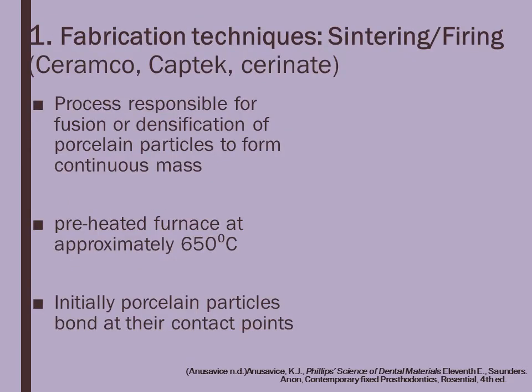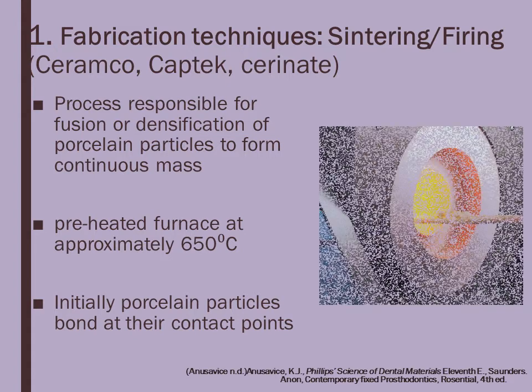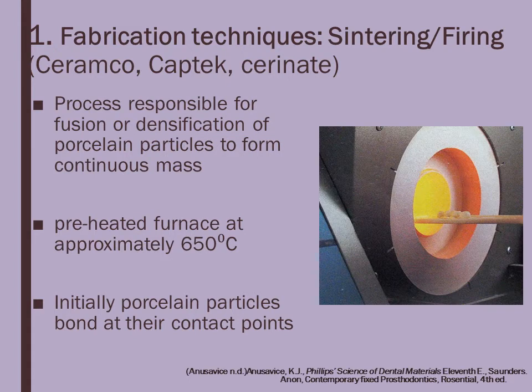So the sintering or firing technique basically is the simplest technique of fabrication of porcelain. It is the process responsible for fusion or densification of porcelain particles to form a continuous mass. As I mentioned, we do the firing or the manufacturing of porcelain in a furnace, a preheated furnace at approximately 650 degrees Celsius. What happens is that the densification of the porcelain particles takes place and it forms a continuous mass. Initially, porcelain particles bond at their contact points and the crystalline growth takes place and they form a continuous mass of the desired shape and size according to your prosthesis.